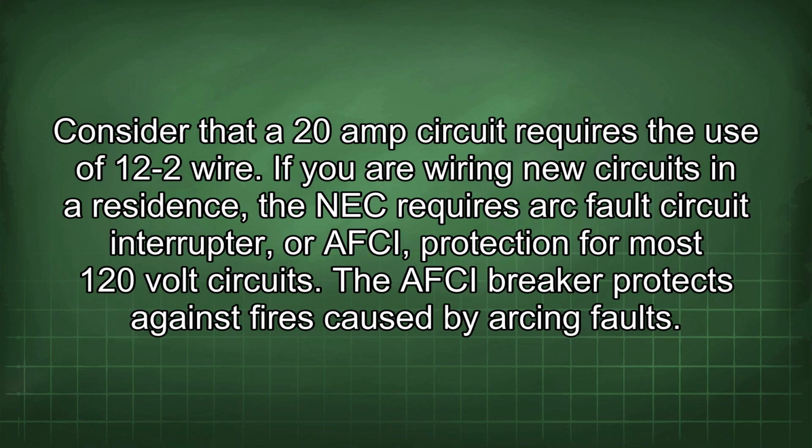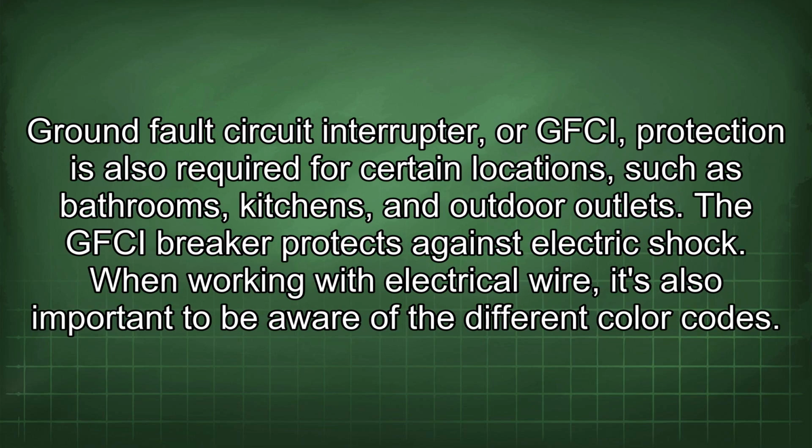Consider that a 20-amp circuit requires the use of 12-2 wire. If you are wiring new circuits in a residence, the NEC requires arc fault circuit interrupter, or AFCI, protection for most 120-volt circuits. The AFCI breaker protects against fires caused by arcing faults. Ground fault circuit interrupter, or GFCI, protection is also required for certain locations such as bathrooms, kitchens, and outdoor outlets. The GFCI breaker protects against electric shock.